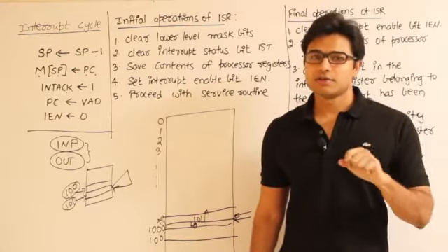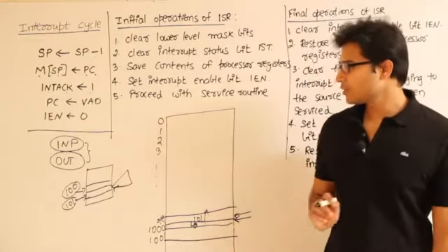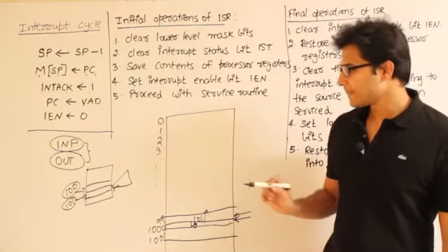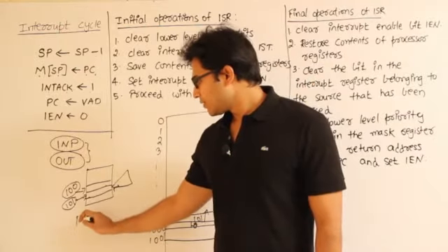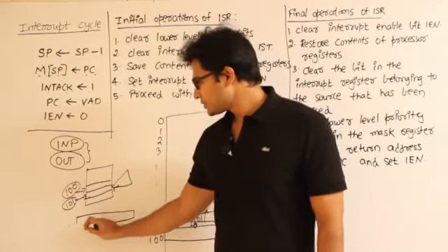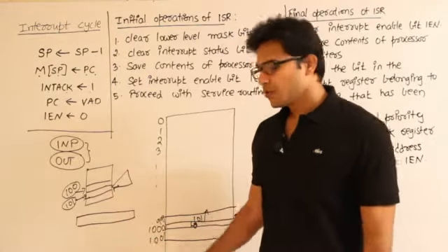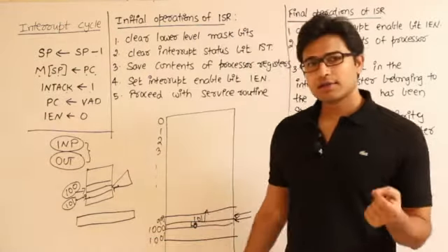The main purpose of that register is giving the address of the interrupt service routine. Now in most computers, how it will be implemented is, as we have seen, the register has many bits, and the priority encoder, please refer to the diagram, provides us with 2 bits, X and Y. Let's say this is X and this is Y.